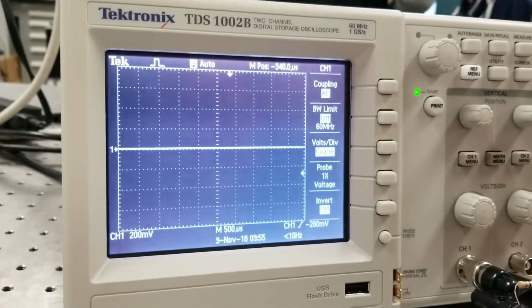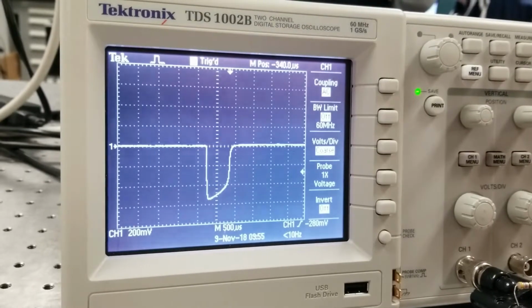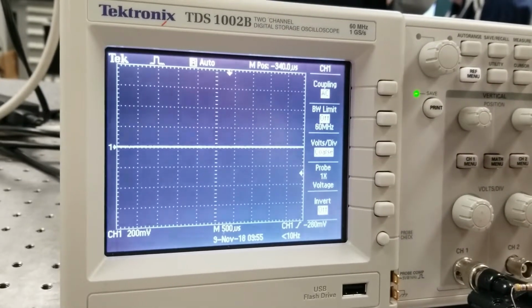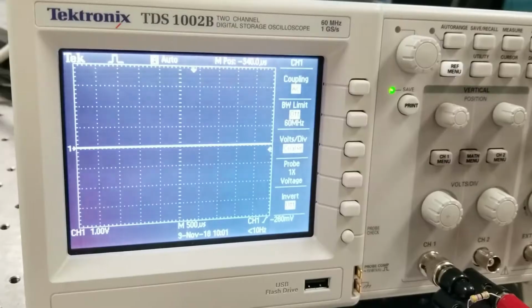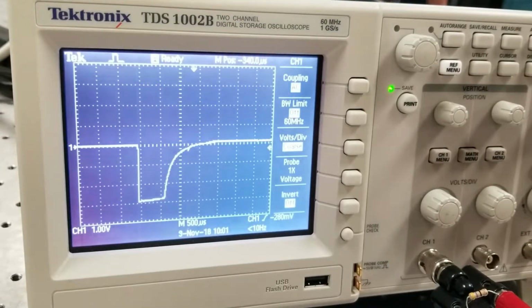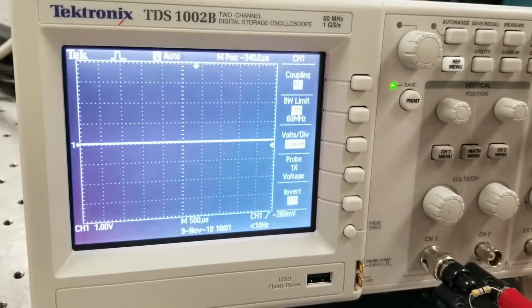Using high power as being closer to the light source and low power as the detector being farther from the light source, it can be seen that the time constant changes, decreasing with lower power and being higher at higher power. The photodiode amplifier causes the decay time to increase at high power and decrease at low power.